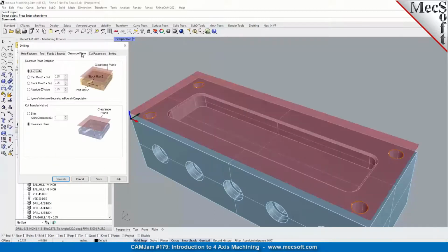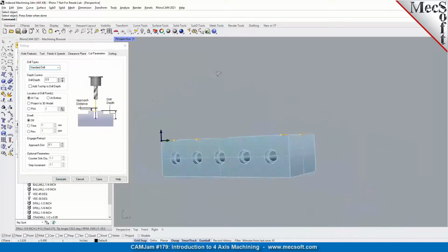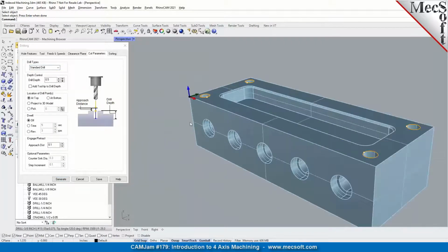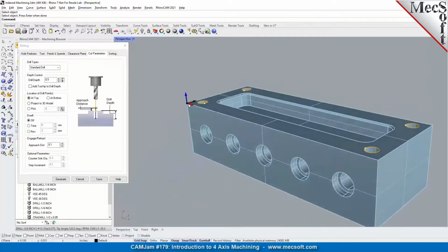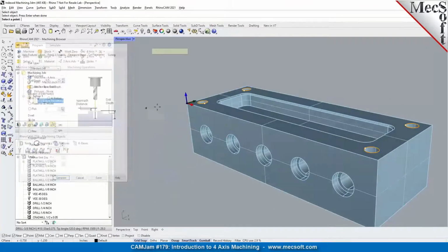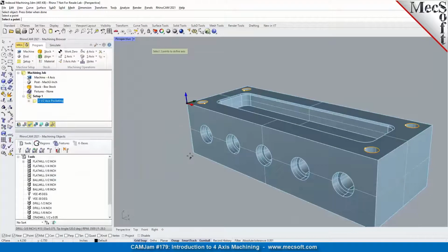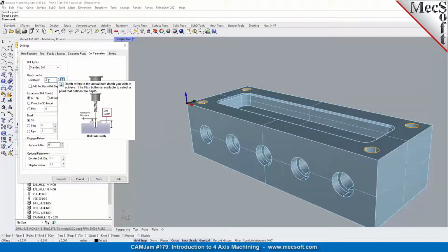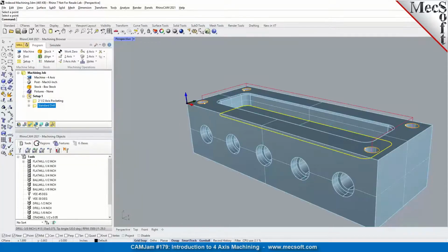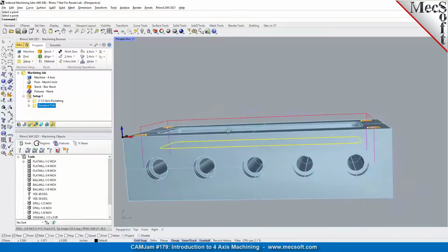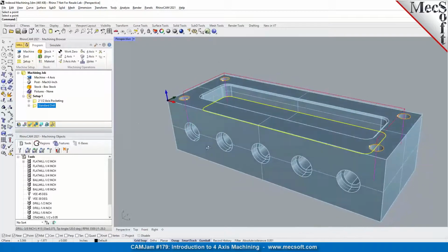And for the drilling operation, I'm going to go ahead and specify the depth in here, so I can just go halfway through since the part has a counterbore on the bottom side, so I don't need to drill all the way through from one side if the tool is not long enough. So I'm going to measure this distance in here, and I could say I only want to go slightly past the midpoint. I can say 1.05, and then specify a sorting sequence, and then generate it. So I'm just going to go past the midpoint or halfway point for the drilling operation in here.